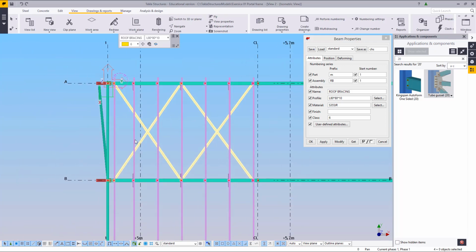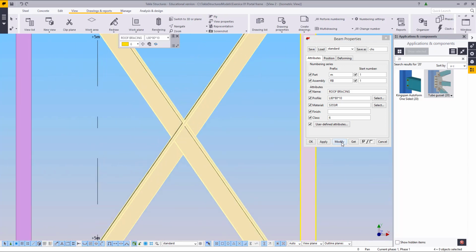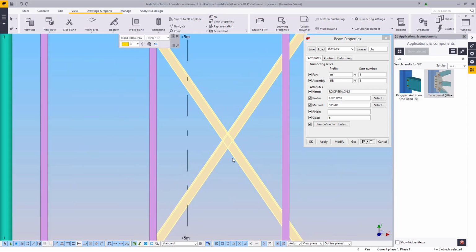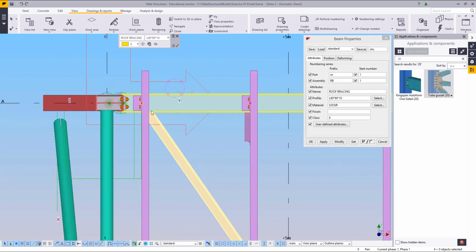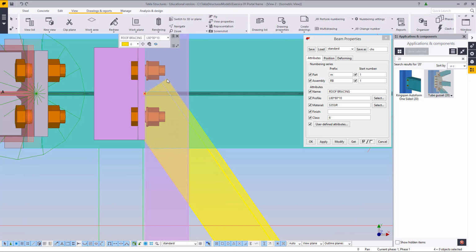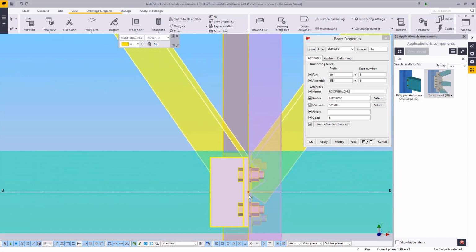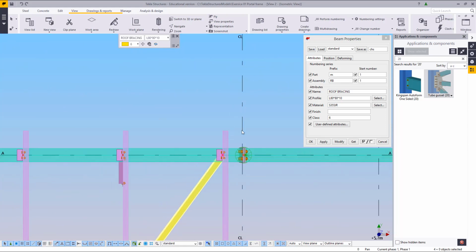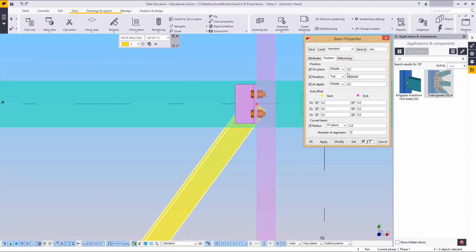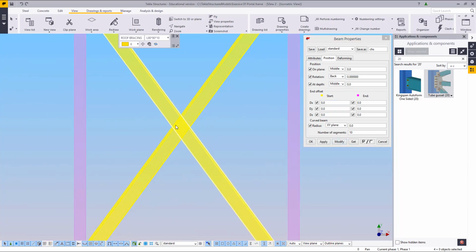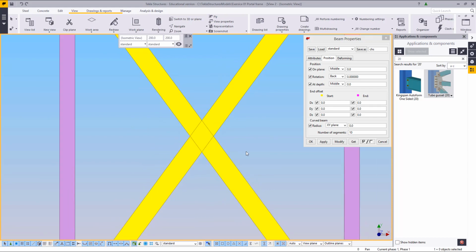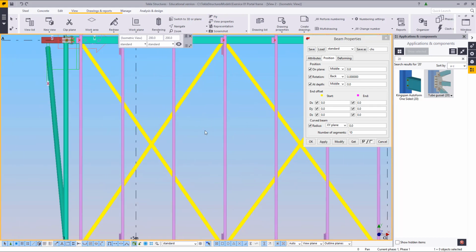Select both of these and modify them, and we'll see them directly from the front. Now, as these are angle line bracings, I want them to be centered according to the SOP. I'd also like them to be facing downwards. Let's see, back, solid, and you'll see they are both facing down.